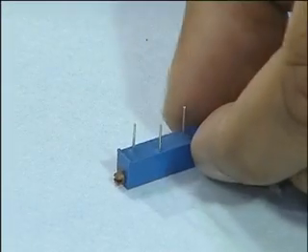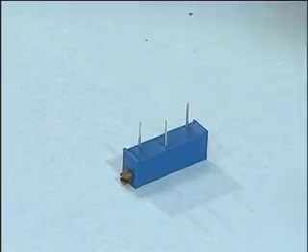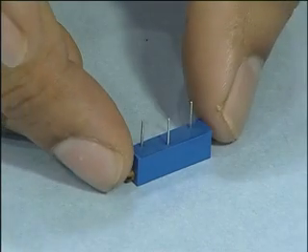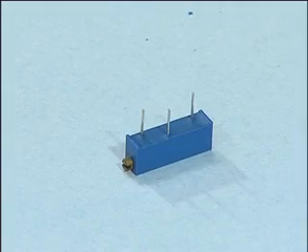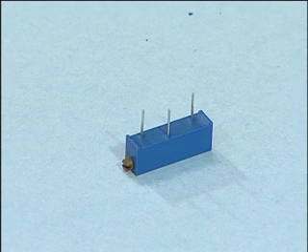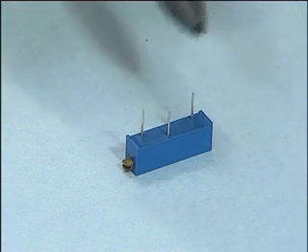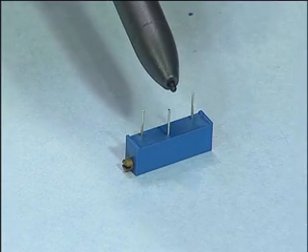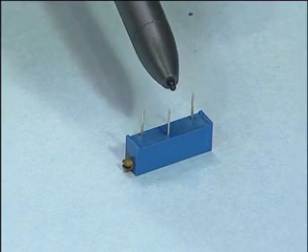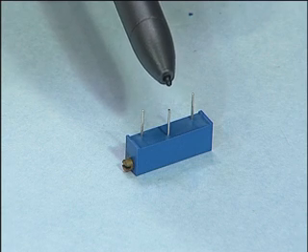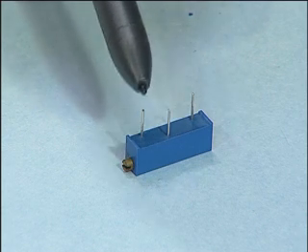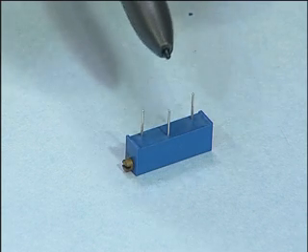There is another type of resistor here, slightly different from the type that you saw. This has 3 terminals. This is a variable resistor, just like we saw in the symbol, 2 terminals and an arrow in between. You have 2 terminals, and the third terminal is the tap which represents the arrow, which varies with respect to either of the 2 terminals.